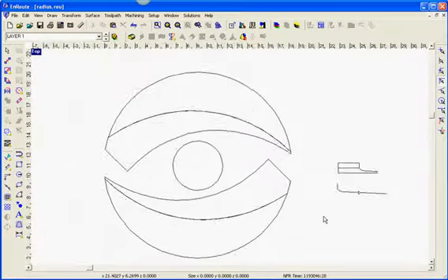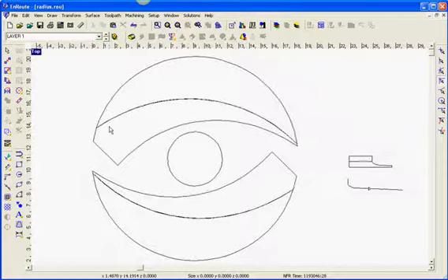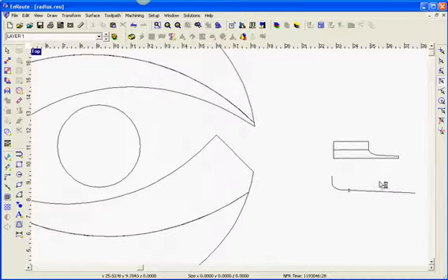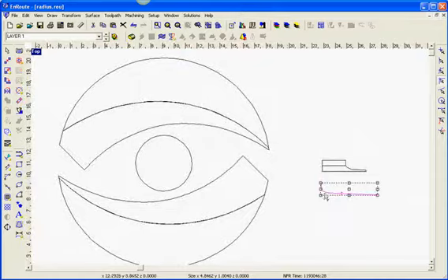Okay, Richard, here's the shape that we want to create a 3D part on, and we want this interior part to be kind of a rounded piece, and this is going to be a flat 1 inch thick part. So what I did is I took the profile, kind of what we had here, and I extended it to be roughly 1 inch tall, and then to be a little bit wider than the widest part here, so I knew we would get full coverage as we swept around here.